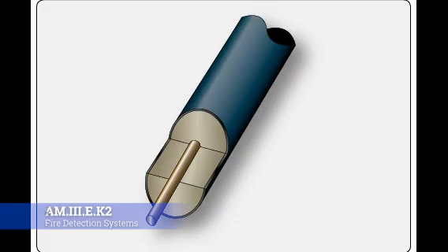It just uses a cylindrical tube packed with thermally sensitive eutectic salts and a nickel wire center, like you're looking at right here. The length of the sensing elements are connected in series to a control unit, and the elements may be of equal or varying length in the same or different temperature settings. The control unit, operating directly from the power source, impresses a small voltage on the sensing elements.